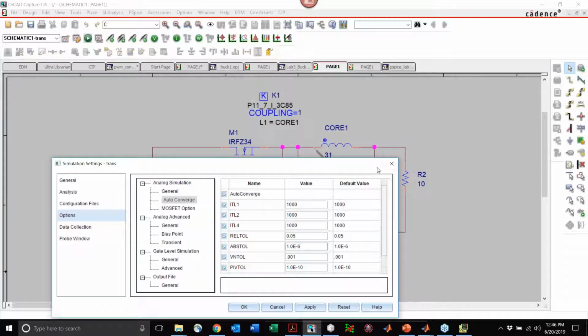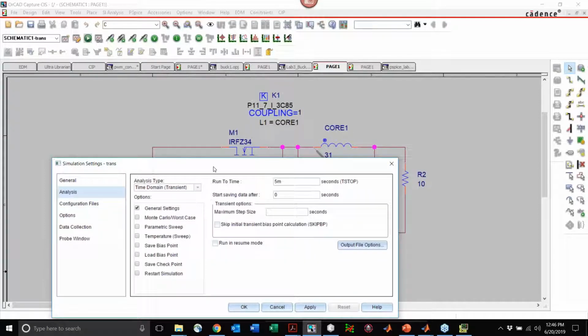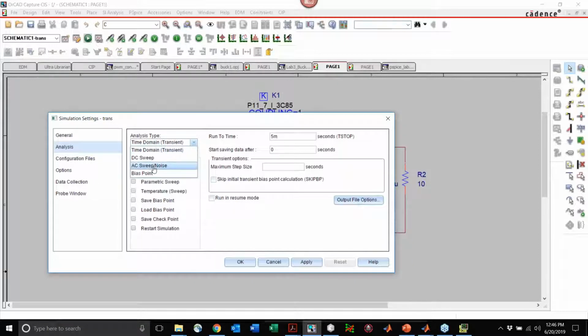Okay, the next one is, can PSpice analyze the circuit stability in the frequency domain? So PSpice does have an AC analysis tool, but it does take small signal approximations. And as I mentioned, if you're able to find a nice sub-circuit model for your power controller, and there's a power IC package that we saw there of SPICE libraries that include many of those average switch models, then you're much better off in simulating your frequency domain response.